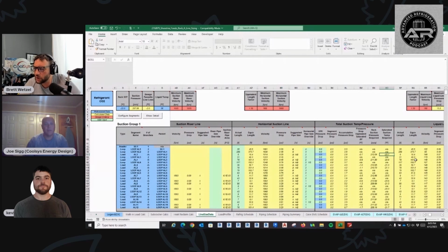You're well within your window of what the compressors are operating at. Well, hold on. No, even go lower. There's one that's negative 21.1. So you don't have higher than negative 22. So how are you doing that with pressure drop? Because that's a lot of pipe. It's a lot of pipe, but with CO2 you get like 7 pounds to every degree of pressure drop. Damn it, that's right. You get a lot of pressure drop in CO2 because it's not a mixed refrigerant. All right, never mind.